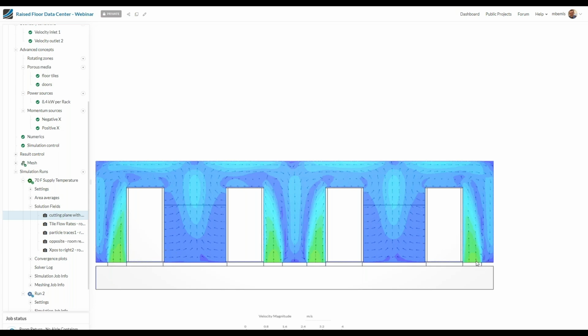If we focus on the far right, we have pretty good velocity coming through the floor tiles, through the servers. The hot aisle is always developed by having servers face each other, and that forces airflow up, and it hits the ceiling. And the problem is here, instead of going back to the CRAC units, it recirculates on itself.